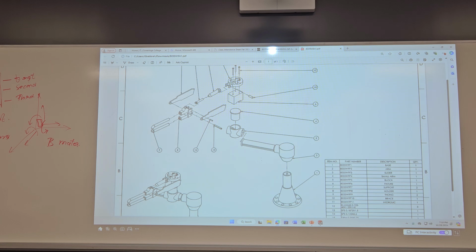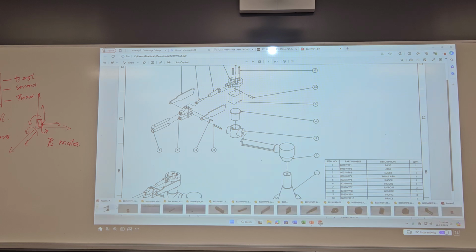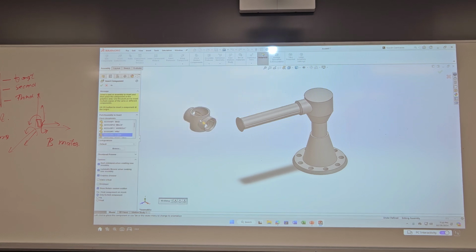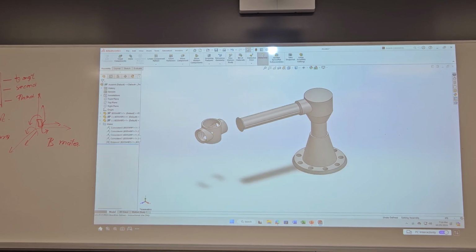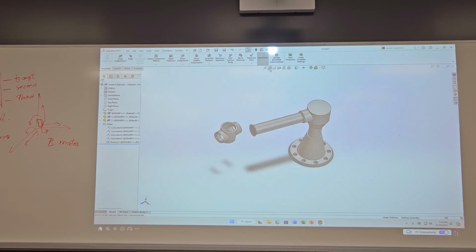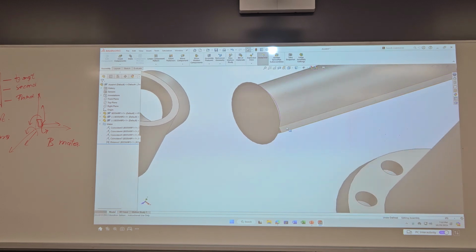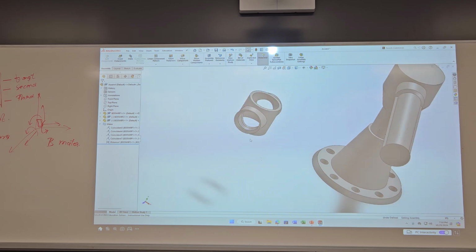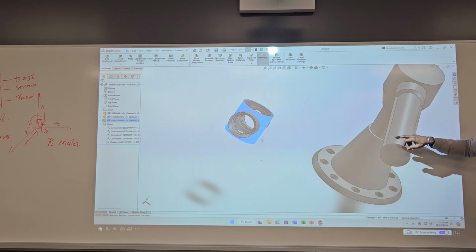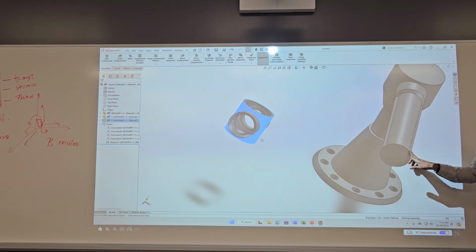Third component is number 3, W9P3, slider. This component needs to ride on this bar here. So let's rotate it to Y. Now if you look at these two parts, there is this little triangle bar on both sides. And on this component, there is a little slot. So this component is riding into this arm and sliding on these tapered faces. That's the design intent.